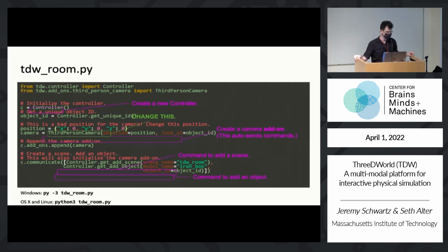So what you need to do is change the position parameter until you can see the object. The hint I'll give you is that Y is up and down, X is lateral, and Z is forward and back. But you'll need to adjust X or Z and definitely Y in order to get a good image.